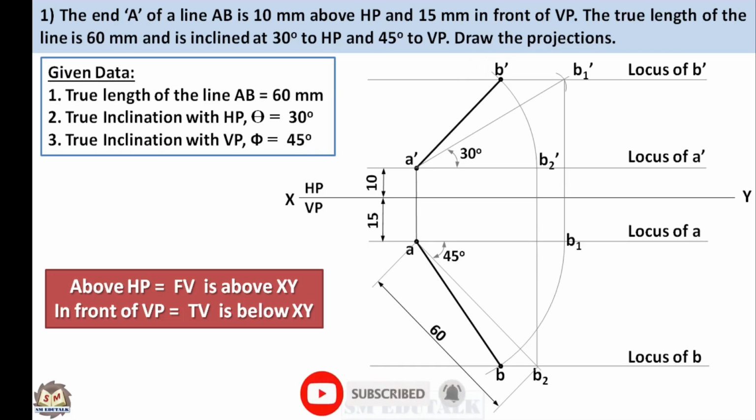As per orthographic projection, the front view and top view should be connected by vertical projectors. In this drawing, on one end, the points A dash and A are connected already. To connect the other endpoints, draw a projector to join the points B dash and B. If this connecting line or projector is vertical, then what you draw is correct. Otherwise, it is wrong. So, connecting the endpoints by a projector is a way of checking the correctness of your drawing.